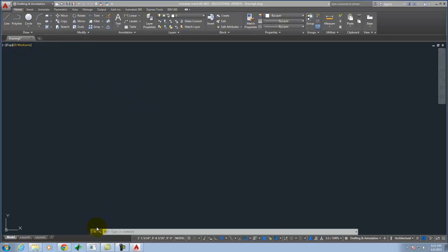Okay. Down here at the bottom, you see this white bar that goes across. This is what's called the command line in AutoCAD. While you can access any one of the tools from one of these ribbons, so for example, I could click the Polyline tool and start the Polyline tool, I can also type down here a bunch of key commands that will allow me to work with AutoCAD. So the faster users in AutoCAD will use more and more command line stuff. You'll do a lot more typing than picking and choosing your tools. It takes a long time to get comfortable with command line things.